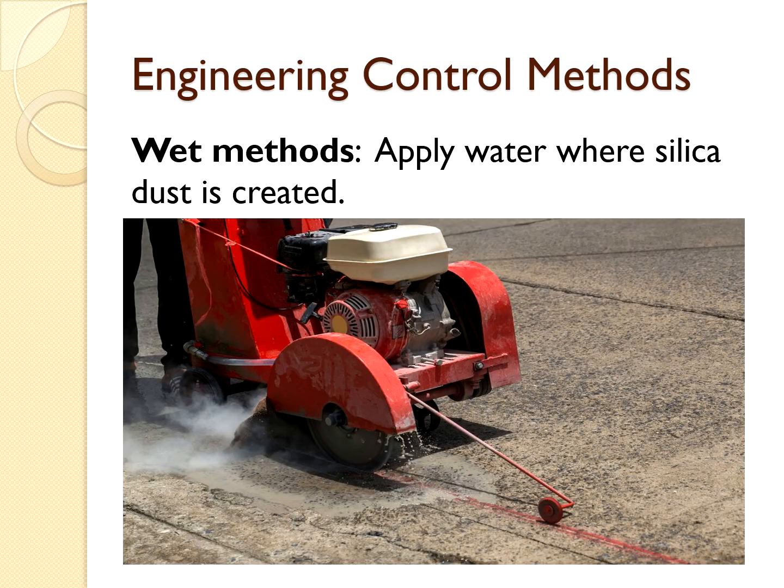Engineering control methods: wet methods. Apply water where silica dust is created. So this is a concrete cutting machine where the water is put on to reduce the dust and silica exposure.